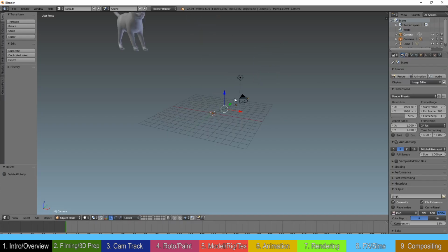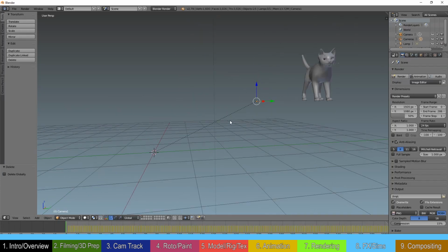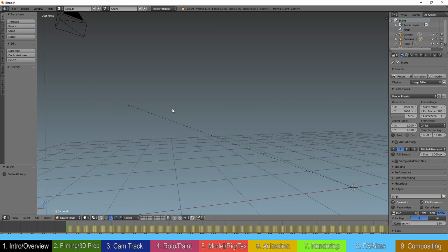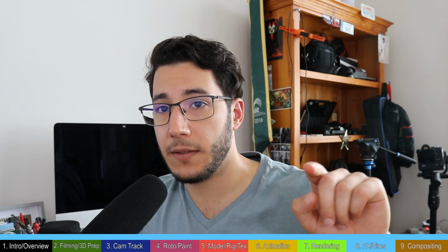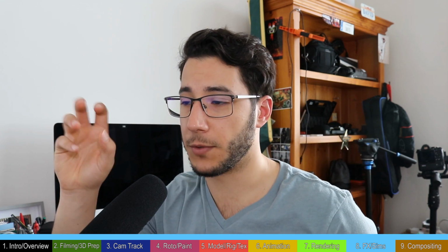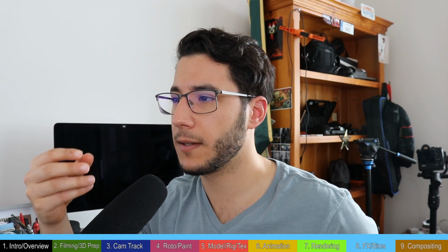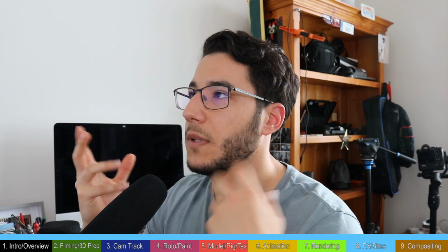It just didn't work. Now, okay, I could be missing something, but surely something so simple should have a tutorial out there, right? I couldn't find any. I was able to get transformations applied correctly to the Blender camera, but the rotations were all off, and the camera backing was a bit out as well, I think. But then I tried importing Nuke's camera track directly into Blender, and voila, it worked. Well, it was about 95% correct.